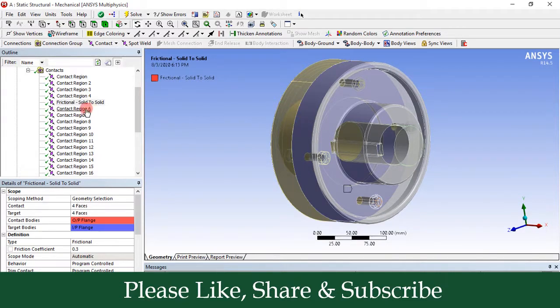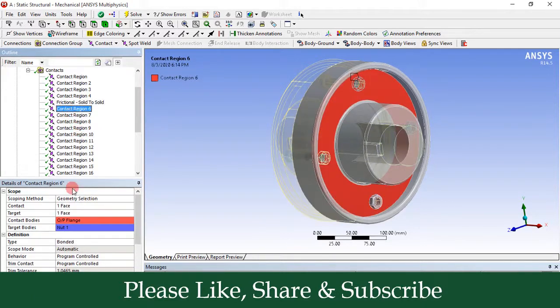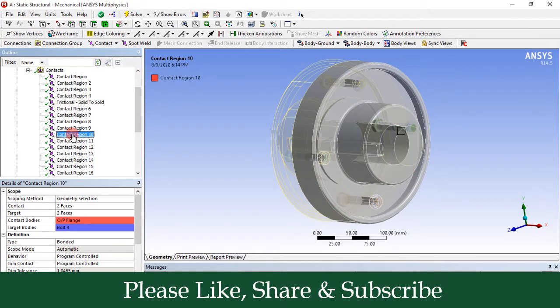So we cannot take the contact between output flange and input flange as bonded, so we have to take it as a frictional contact. Other contacts are bonded type. This is the output flange and nut 1, it is bonded. Again, output flange, nut 2 bonded. Then output flange, nut 3 bonded. This is output flange and nut 4, it is a bonded type of contact.